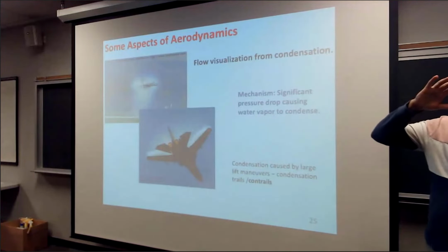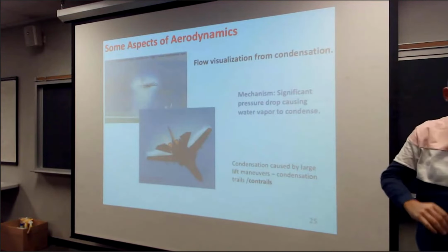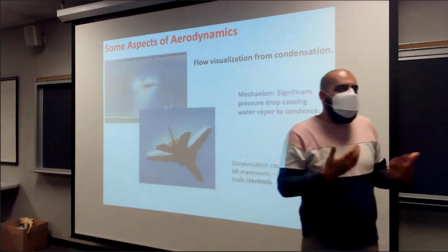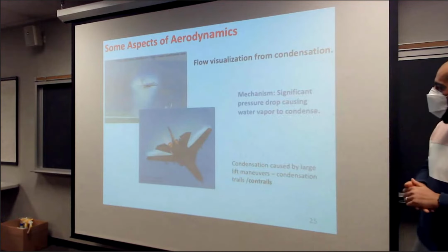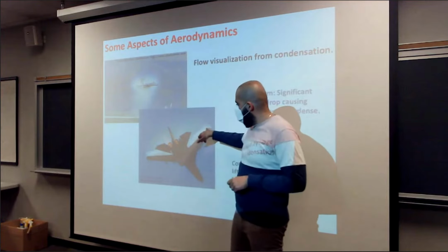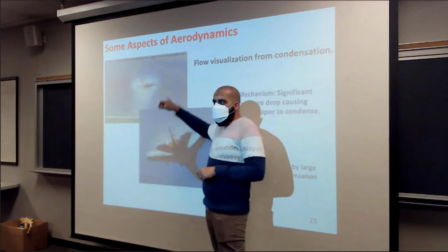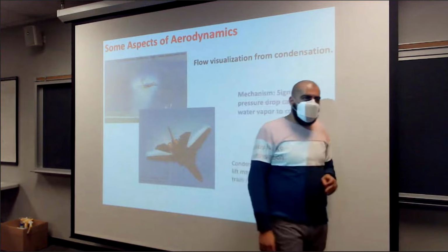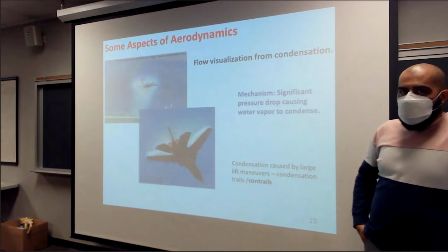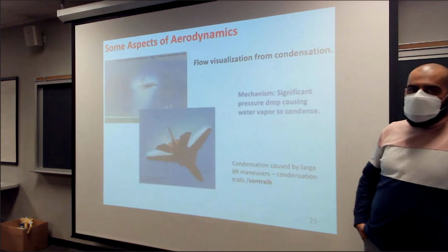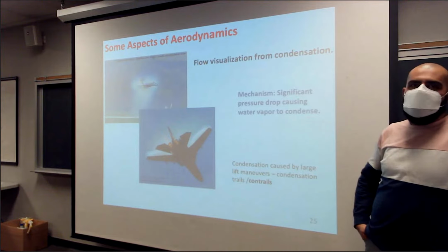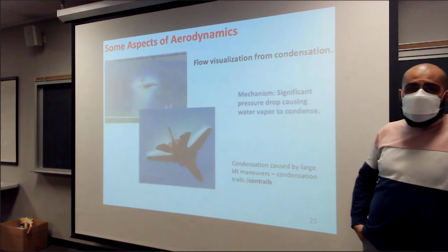The idea is that when an aircraft breaks the sound barrier, or starts flying at a speed higher than the speed of sound, you're going to see a fog on top of the wing. The shock wave is going to create a pressure difference, so you're going to have a huge temperature change and pressure change after the shock wave.